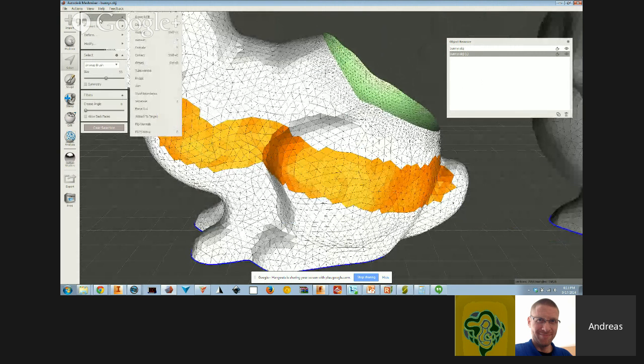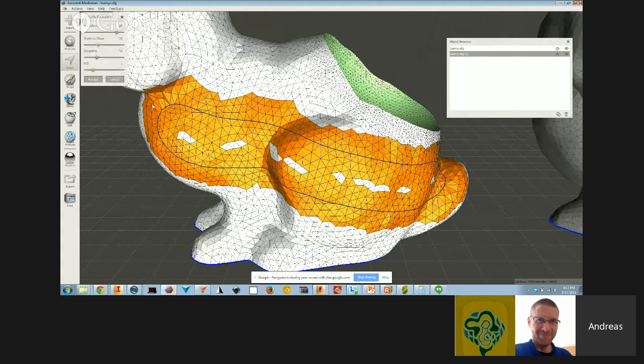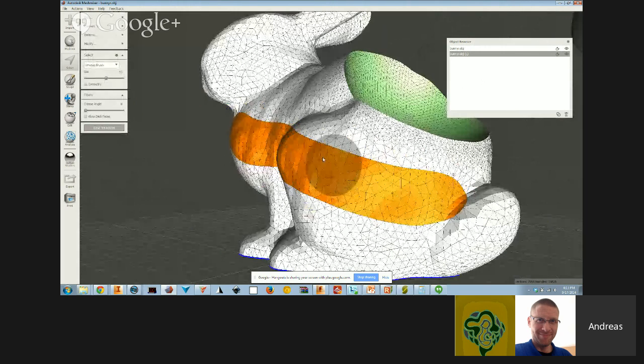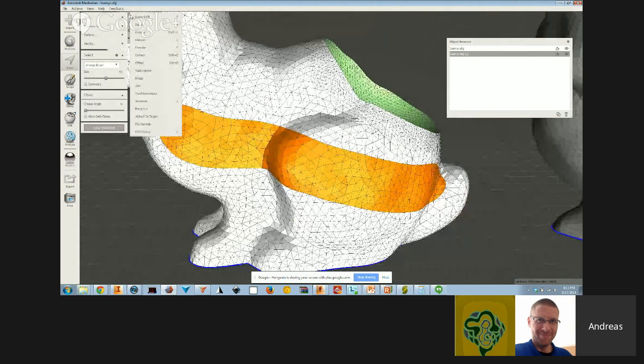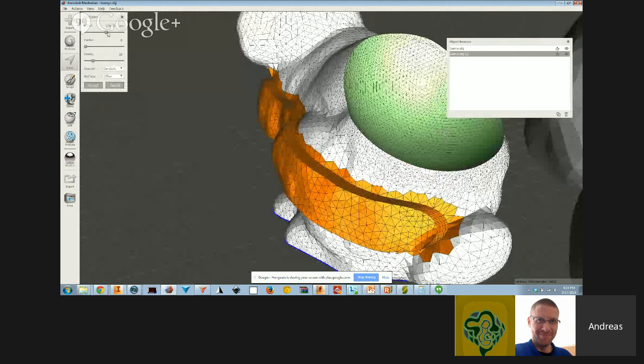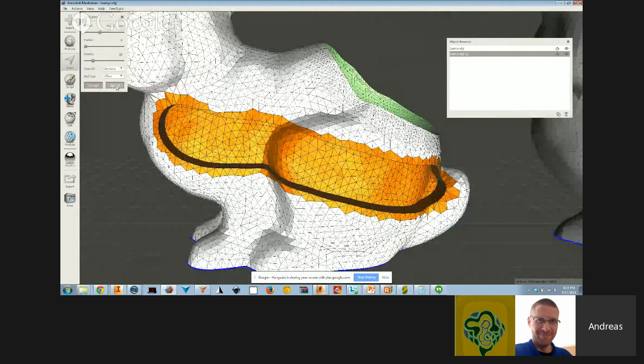One that I commonly use is to go to Modify and Smooth Boundary. And watch what happens to these sort of faceted faces here. I can smooth them out, with some of these parameters. I have some control here, and accept that. And now I have updated geometry based on that selection, and again, with faces selected, I can do, let's just show an extrude, for example. Something like this, right? So I selected the faces, I smoothed the boundary, and then I extruded those faces.